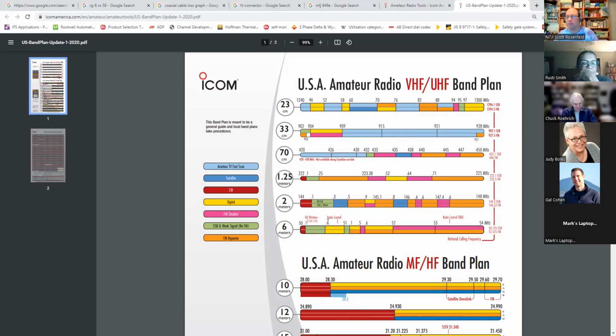So it's weak on the receiving side, not on the transmitting side. Correct. Well, it could be both, but usually it's on the receiving side. The advantage of single sideband over FM is that single sideband has a narrower bandwidth. The approximate bandwidth of single sideband is 3 kilohertz. The approximate bandwidth of VHF FM is between 10 and 15 kilohertz.